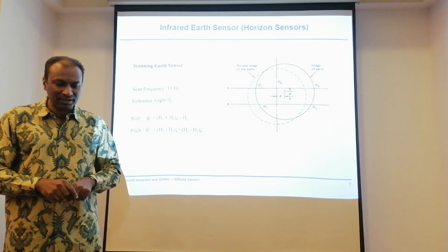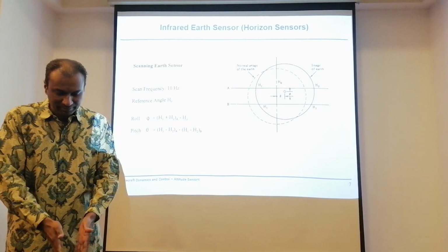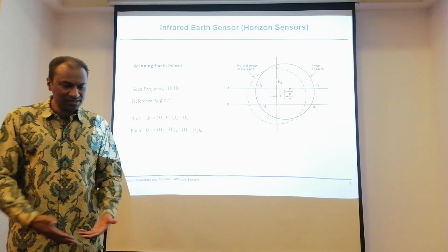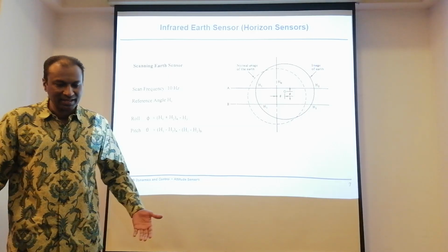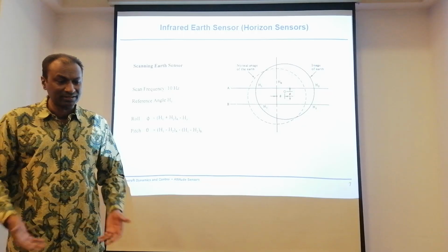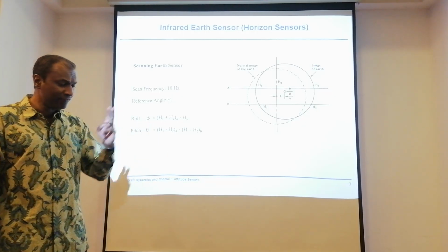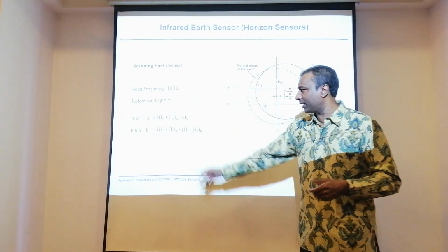But unfortunately, when you look down towards Z, that is exactly on the planet Earth. That means it's all basically the terrain. You can see sea, etc. So you can't detect, you can't actually have a horizon. So you can only see the land. You can see it all, but you can't have the horizon. Which means that we can successfully have a detection of two major axes, roll and pitch.